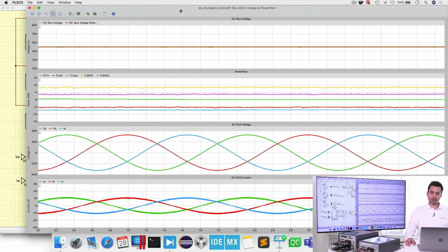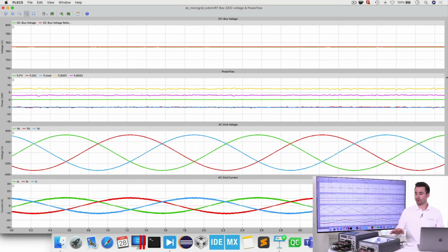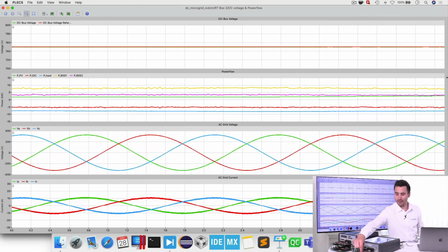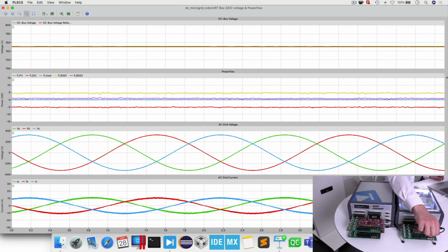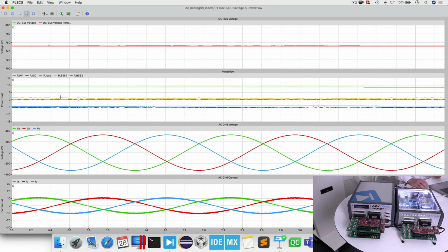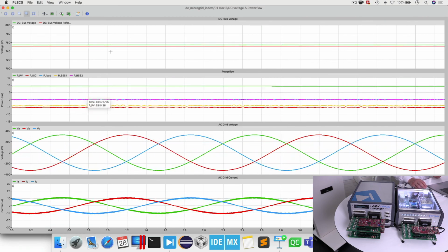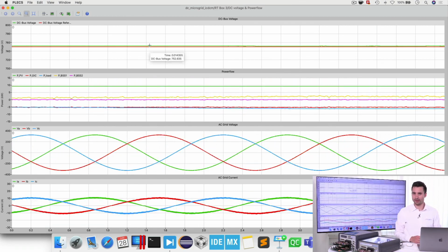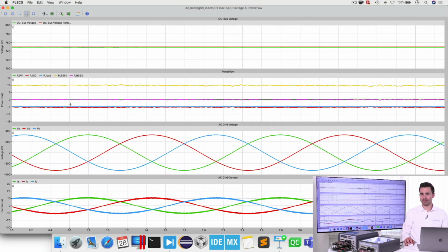What we can do now is also, let's say, to test how our system reacts if we lose one battery storage system that controls this DC link voltage. So also there, I can then just toggle again here the dip switches, so to make this system trip. And you can then see that the power output of this battery storage system 2 is going to 0, but the microgrid remains stable and we are still able to operate it. So now the DC link voltage is controlled by a single battery storage system.